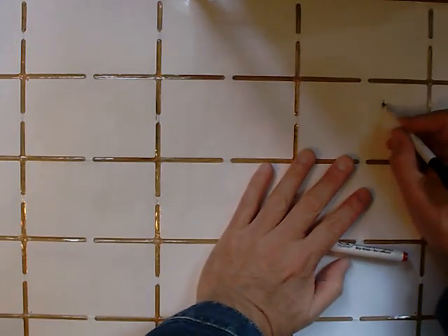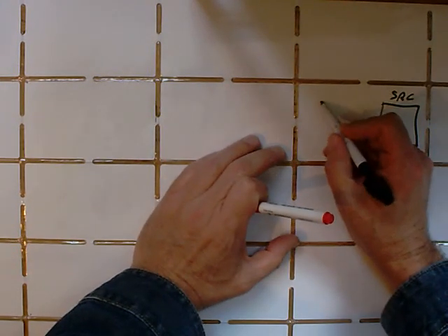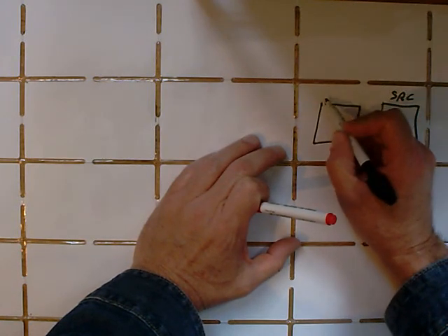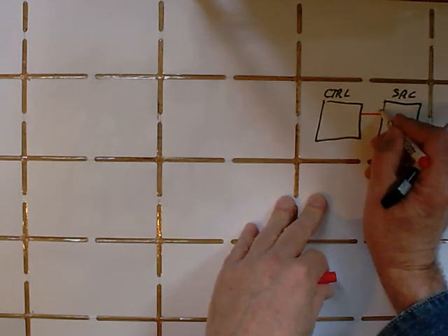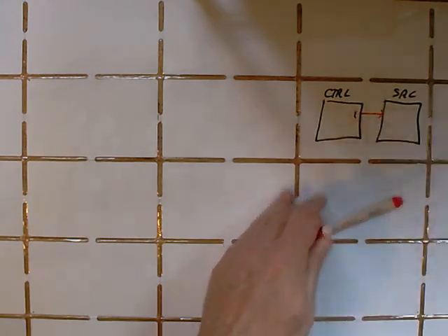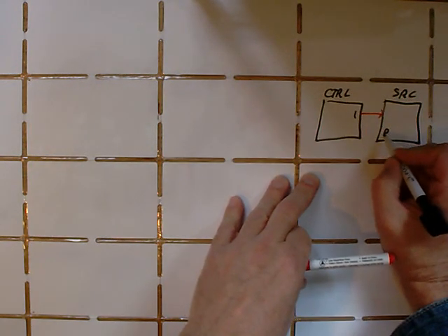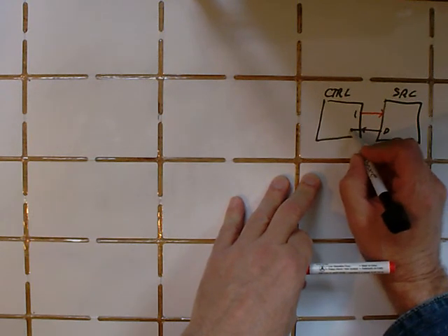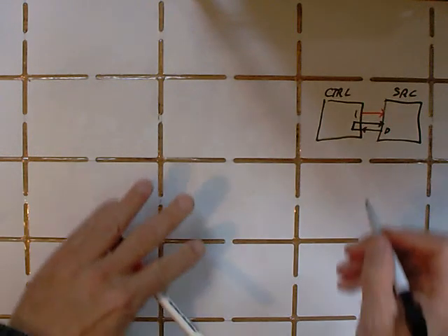As a further look at C-mode behavior inside the cell matrix, let's consider this case. Again, we have a source cell with a truth table that we presumably consider to be interesting, and we have a controller sitting next to it, which places a 1 into the source cell's C input. The source cell is now in C mode. Its data output goes into the controller. The controller recirculates it back in so that there's no change to the source cell's truth table.